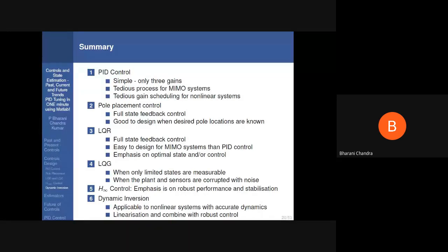The big question is, how do you define these operating points? That is very difficult, and how to choose them? You should have complete information about the system. For example, if it is a DC motor, then I can say that one set of PID controller will work for 0 to 500 RPM, for 500 to 1000 another set of controllers is required, for 1000 to 1500 another controller is required, and so on.